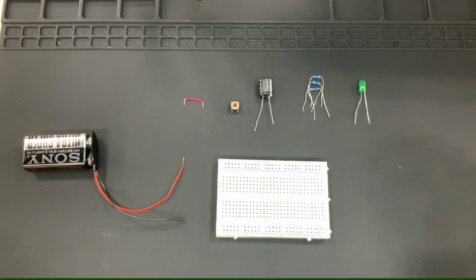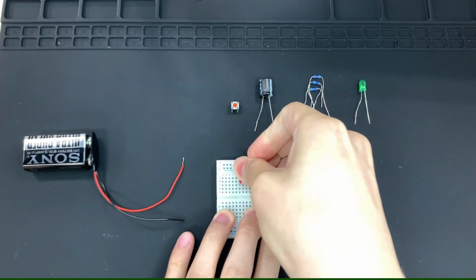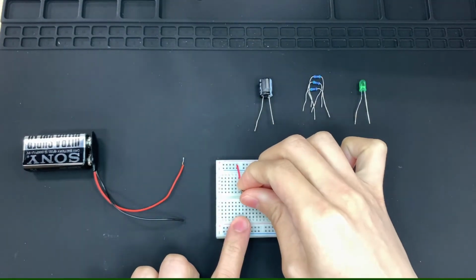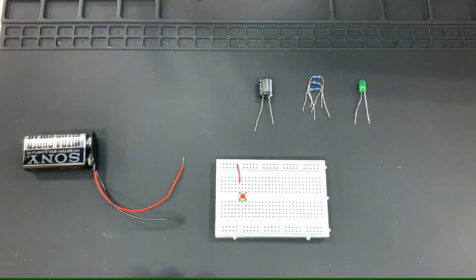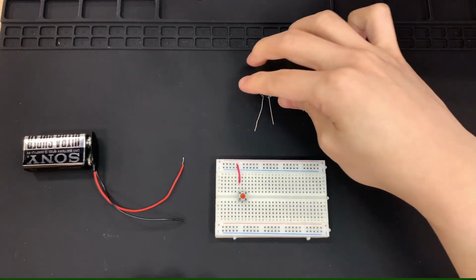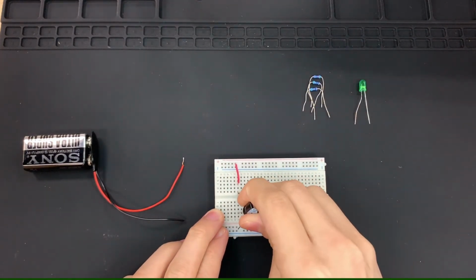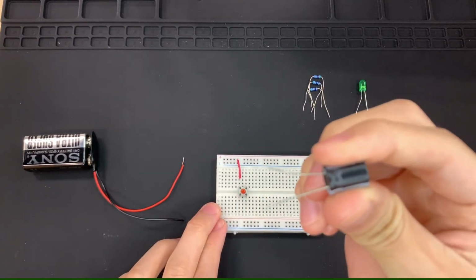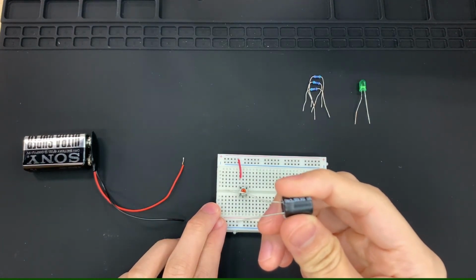To get started, let us first get the jumper wire and connect it in the following order. Next, we will be using the push button. We'll connect it to the power supply. Thereafter, we will be getting the aluminum capacitor of 1000 microfarad connected in the following order. Do take note that the longer pins will have to be connected to the power supply, the shorter pins to the ground.